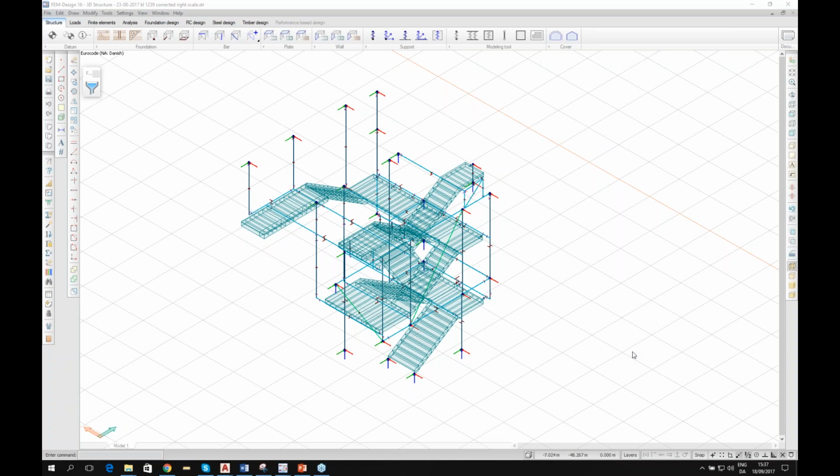This is difficult to detect, and as you write, you need to take a look at the displacement figure to find these things. So again, just focus on modeling your structure exactly, so you're sure everything is connected. Especially pay attention to the no snap function you have in FEM-Design, because in AutoCAD you can have several lines with just 0.1 millimeter in between them.